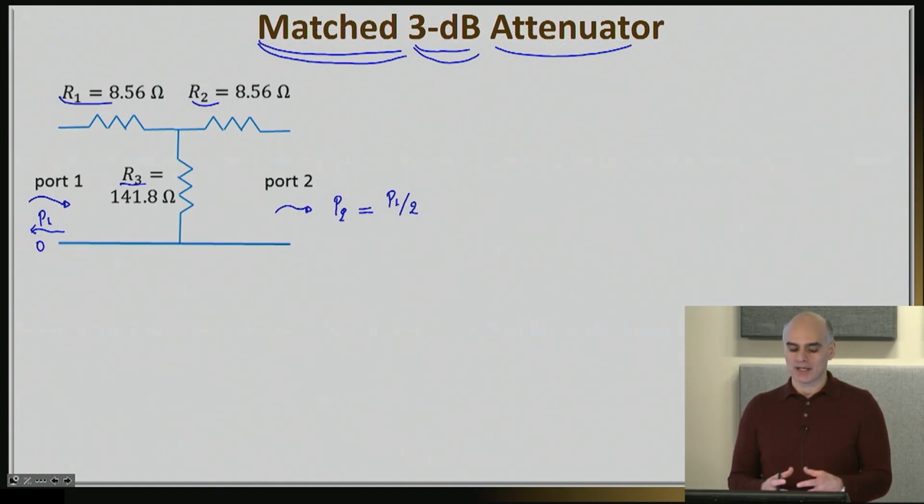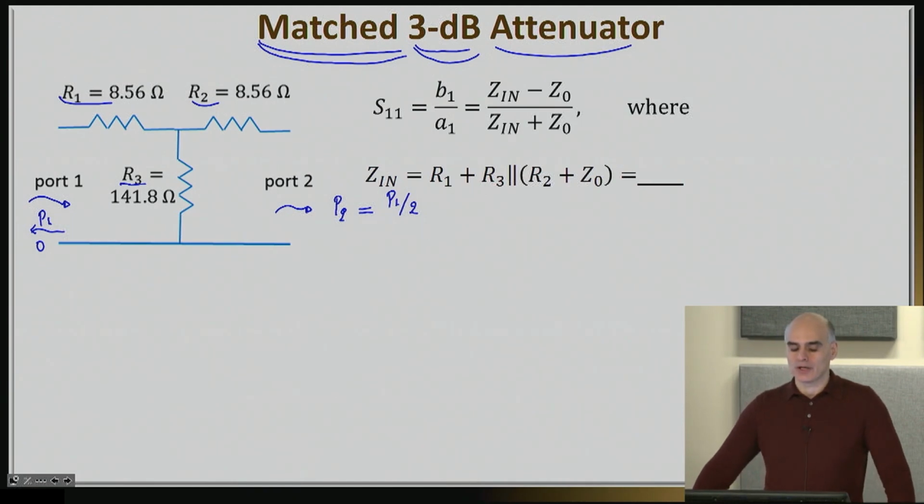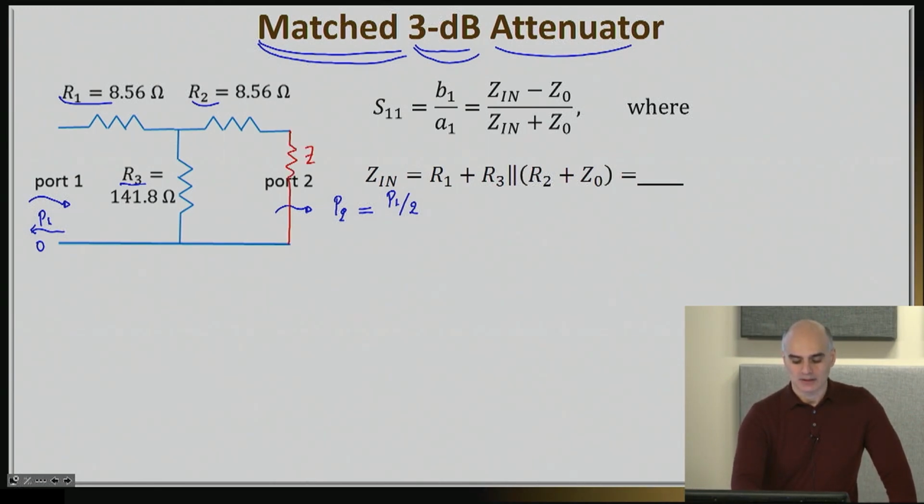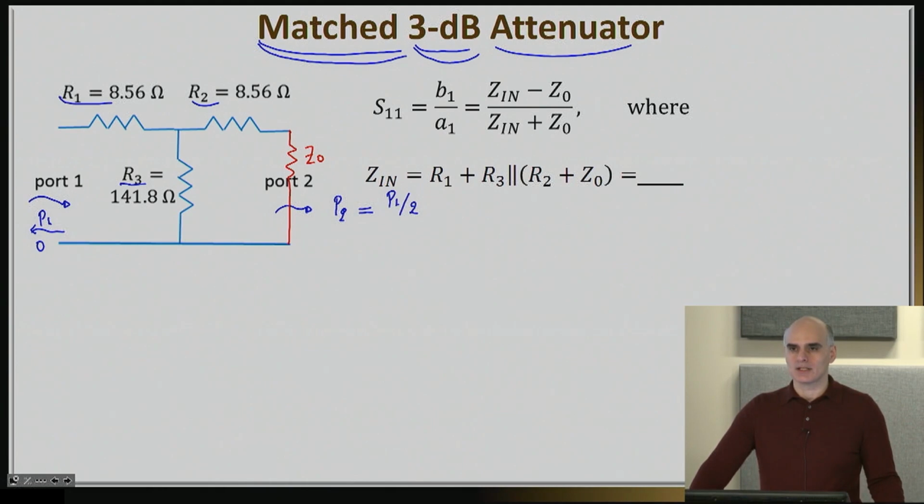There is a way we can actually solve these equations that you will see in a minute and get these numbers, but I just decided to give you the numbers and simply focus on calculating the S parameters for this network. So let's go through our calculation as we have basically seen before. I'm going to assume that port number 2 is terminated to its own characteristic impedance, Z0, and then I'm going to calculate S11. Now you might say, one second, what exactly is Z0 here?